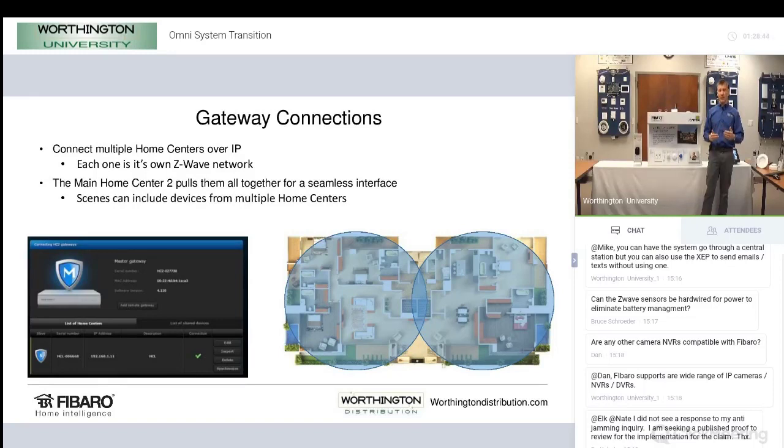With Z-Wave, there are some limits to how big of a job we would do and how many devices we do. Typically, and this varies on system, it varies based on people's opinions too, I think. We don't like to see Z-Wave used beyond like 150 devices on a network and beyond that 5,000 to 7,000 square foot range, depending on the construction of the building, whether it's more of a masonry or more of a wood structure and what's in the walls. And like I said, that varies, and it depends for a number of reasons.